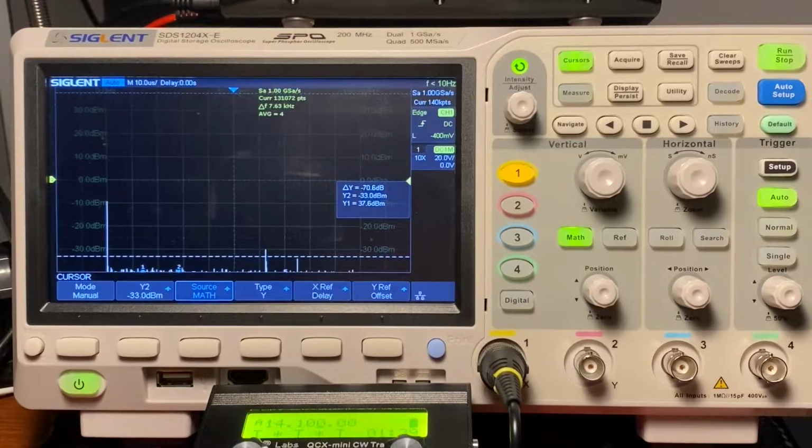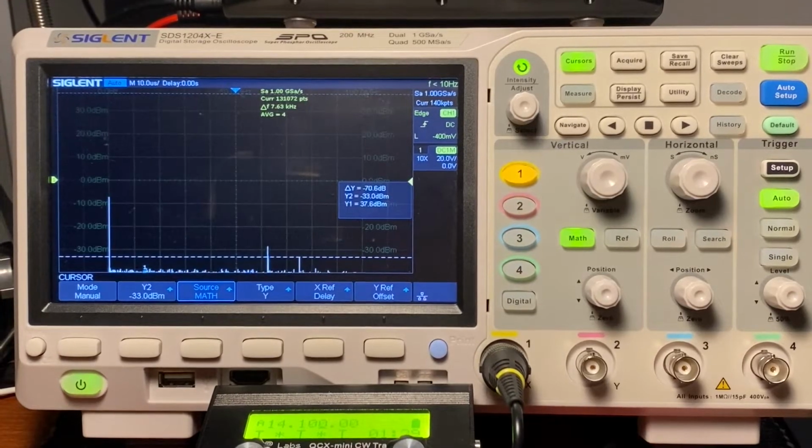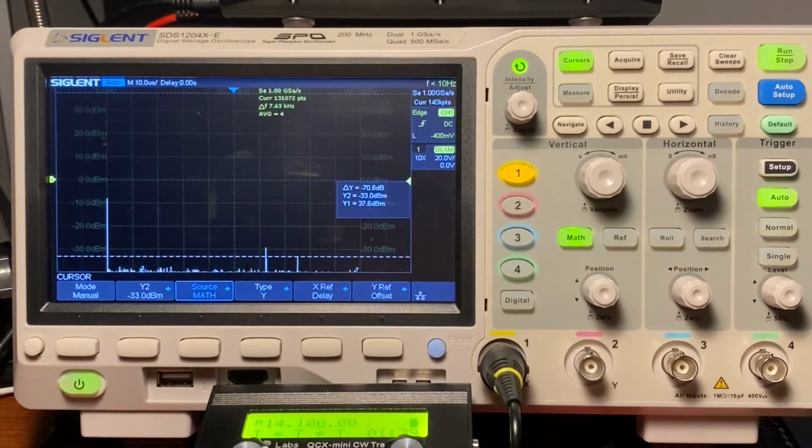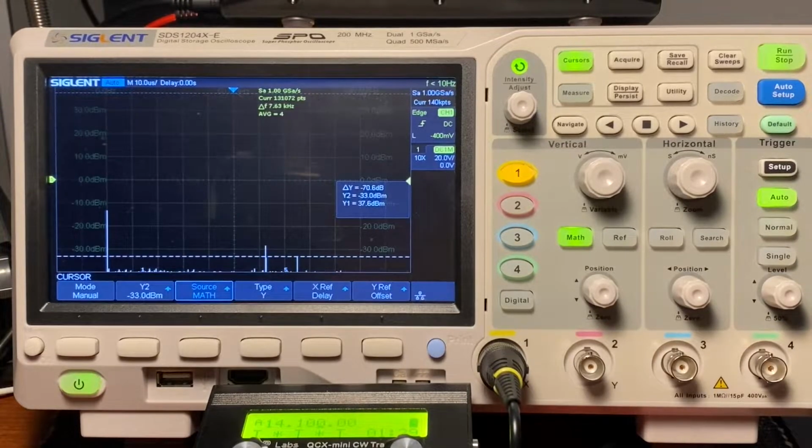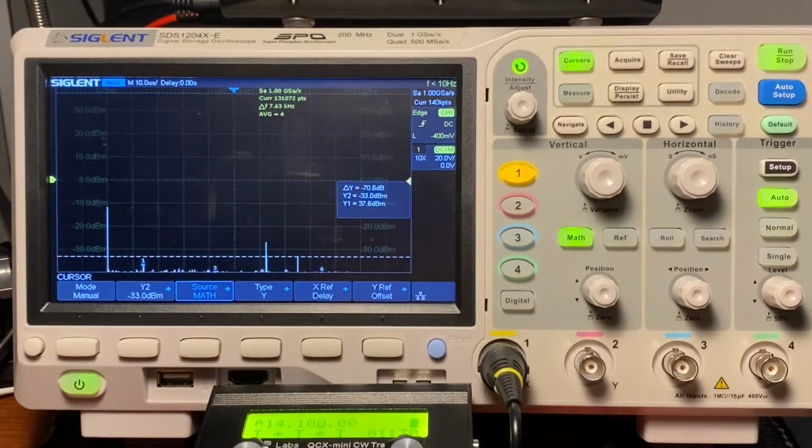This is caused by the local oscillator leakage coming from the transmitter. This is an actual measurement that is correct, although it is very, very faint. This is a problem that is common to all direct conversion receivers, and it is not an issue, and it's perfectly legal. But you may have also noticed that you hear that in a receiver tuned to the same frequency.